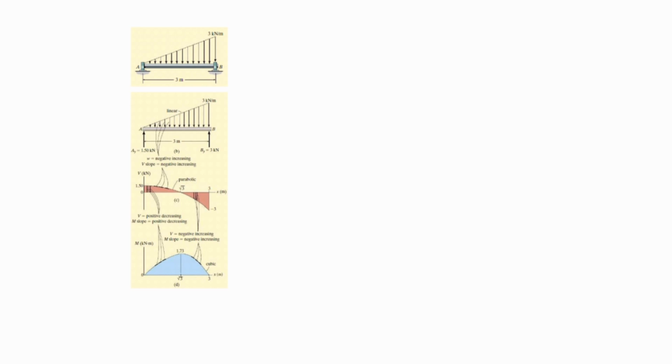Here what I have is a beam which has two supports and a distributed force which is like a triangle over there. As I said, the first step in all of these problems is finding the reactions. And actually what we have here is like this. We have two supports and two forces could be found based on that.